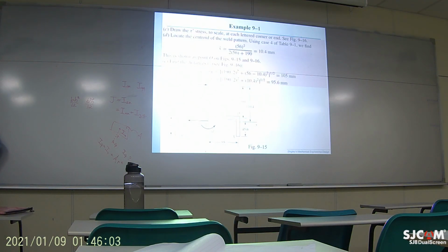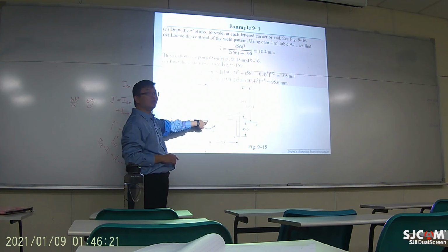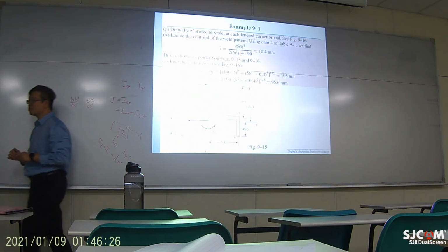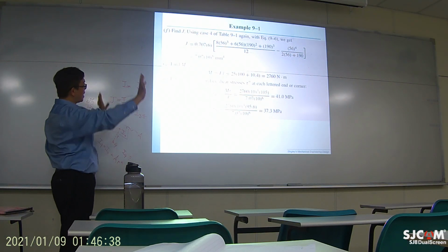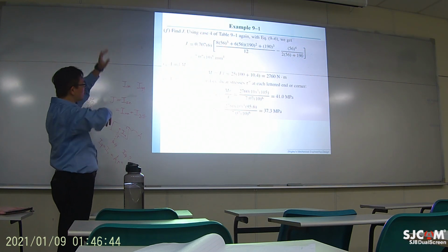And the interesting part of the rotation is you need to find out where your rotational center is. From here, you need to know the rotational center is right here. So you use the centroid to figure out where that point is. Once you have the center, then it's basically computing the shear stress that follows this rotational direction, the tangential direction.